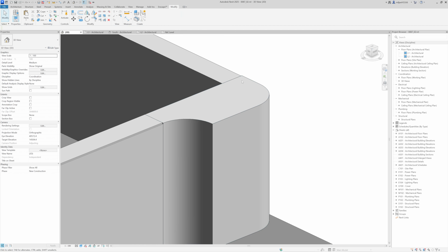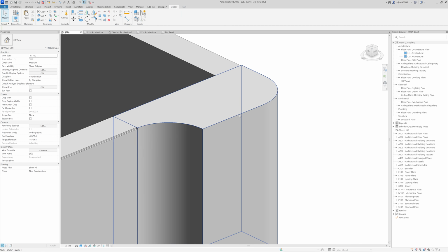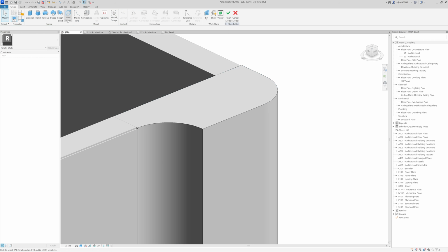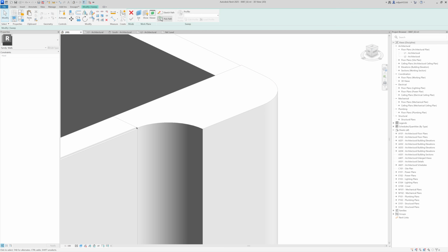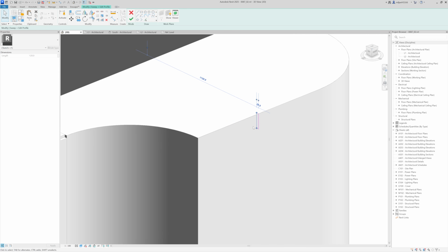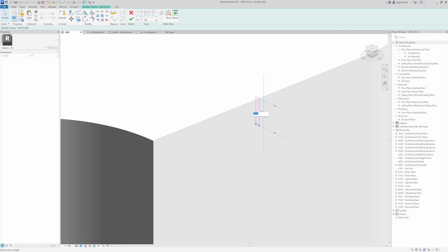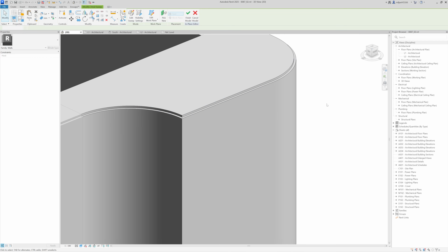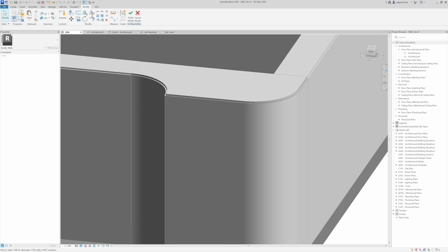And you saw that we have a problem placing it here, so the way to fix it is to select this model in place, go edit in place, and then take a void sweep. So for a path, pick this as a work plane, and then pick a path, and create a profile, which is 20 by 20. So done.